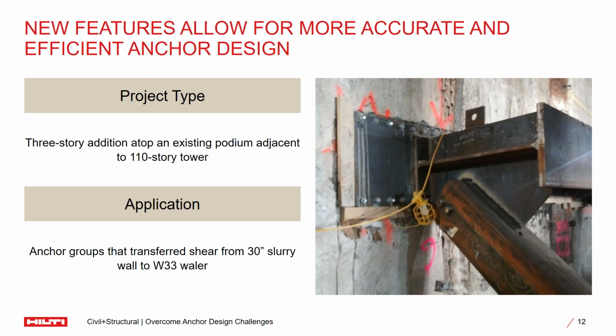So when you designed this, was your first design that you had put into the software working? No, we actually had to go through a couple different iterations to come up with an anchor group layout that would work, and also met the site constraints of what the contractor encountered in the field. There is rebar in the existing slurry wall, so we did have to make some adjustments to the anchor group layout to accommodate the design. Gotcha. Thank you for explaining that.